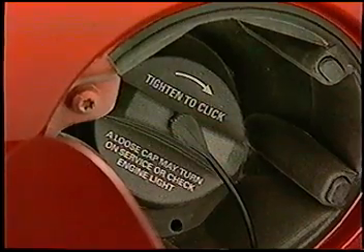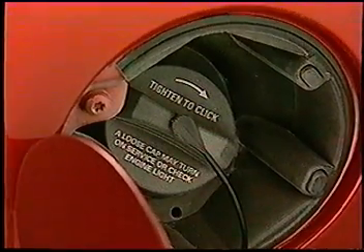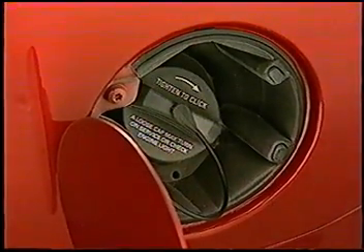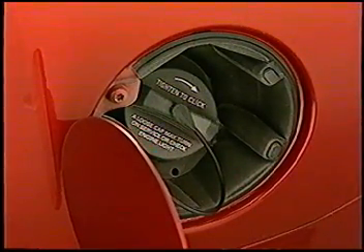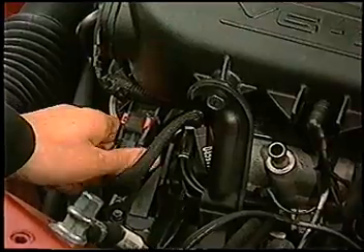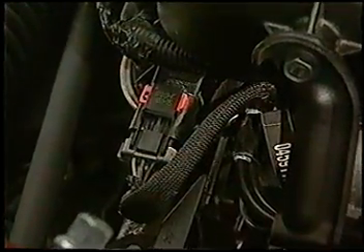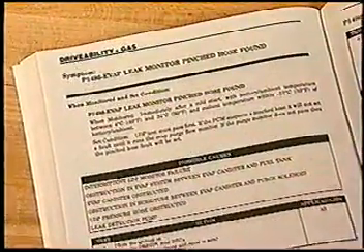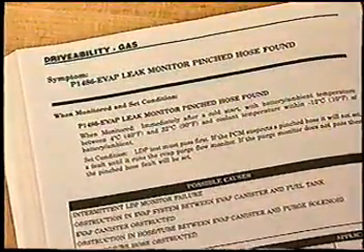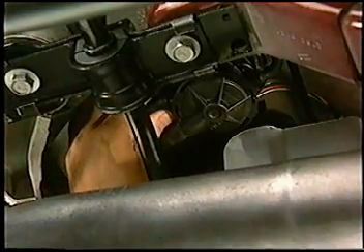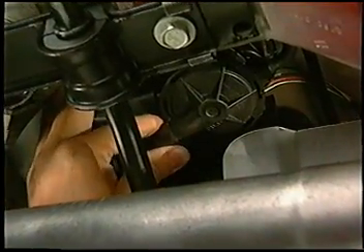First, beyond just checking for tightness, you want to make sure the gas cap is in good condition. A loose gas cap could cause a small leak to be detected, but so could a defective one. Before replacing any components, you want to check connections to make sure they're properly seated. And if the trouble code indicated a pinched hose, like P code 1486, you'd want to inspect the evap system hoses and tubes for pinches or blockages.